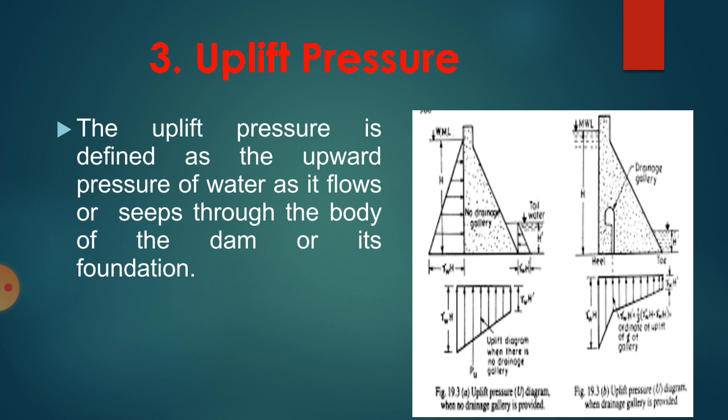The third force is the uplift pressure. Uplift pressure is defined as the upward pressure of the water as it flows or seeps through the body of the dam or its foundation. Here, the area over which the uplift pressure acts has been the question of the investigation, and there will be two cases.